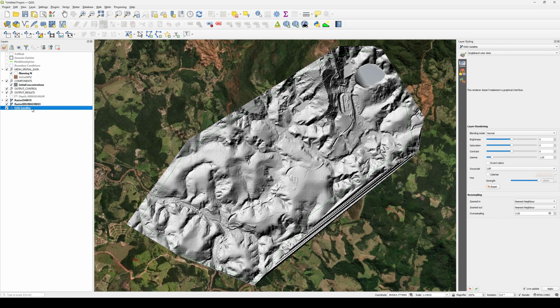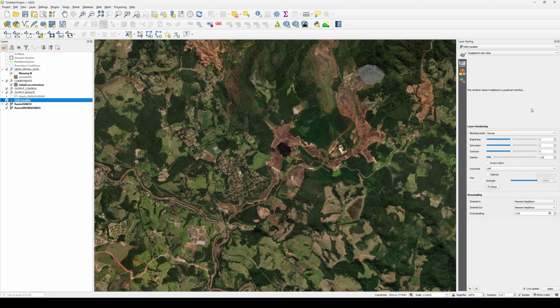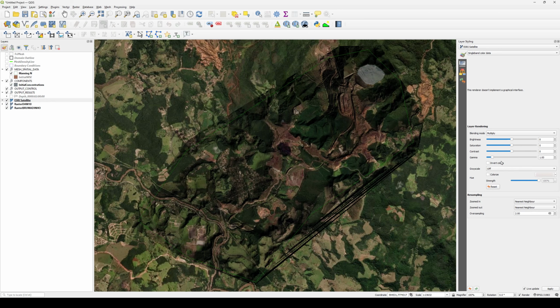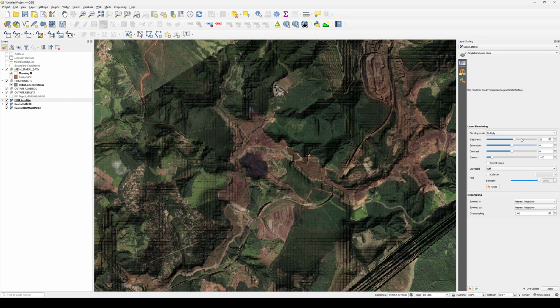And to make it even prettier, I'll put the Esri above everything else. And then here in the raster, or rather, I think the Esri, I multiply this. And I can kind of give it the shading from the raster. This looks good if you were zoomed in, but it darkens it quite a bit. So you can mess with the satellite and give it some brightness there.